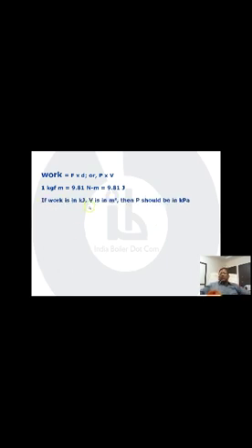Okay. Now one thing is important to remember: if I am finding out the work in kilojoule and I am using PV as the equation of work, where the volume will be in meter cube, the pressure will always be in kPa. Please remember this. You cannot take any other pressure unit if the work is in kilojoule; the pressure has to be taken in kilopascal, right? That has to be remembered.